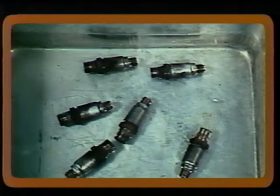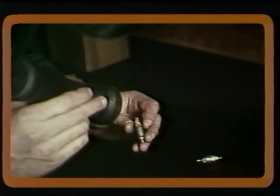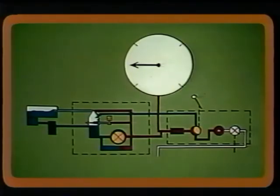Clean the nozzles by soaking them in acetone or MEK and flow them out in the direction opposite normal flow. Examine them with a light to be sure that there is no obstruction in the passages. With all of the nozzles clean and properly installed, connect an accurate pressure gauge in a T-fitting between the fuel control and the manifold valve.